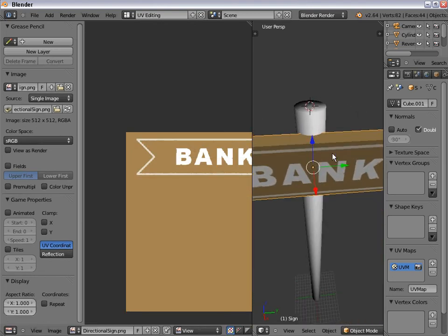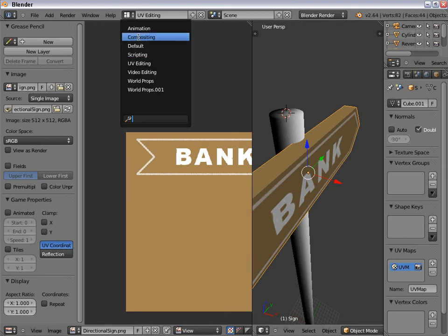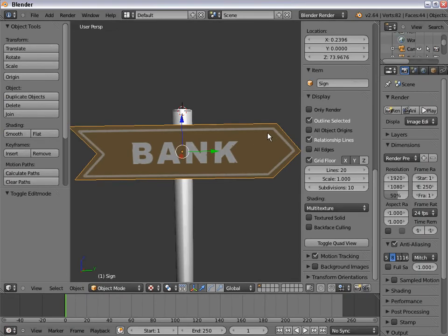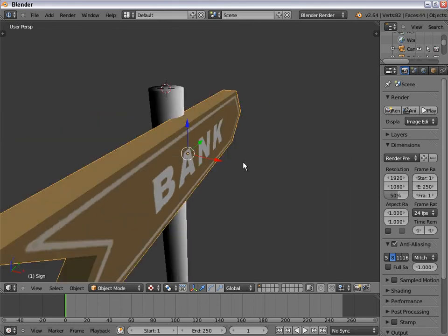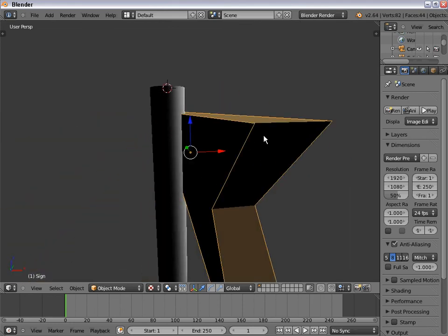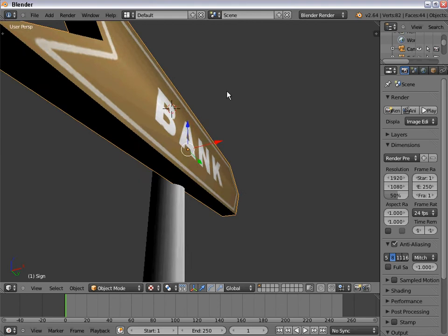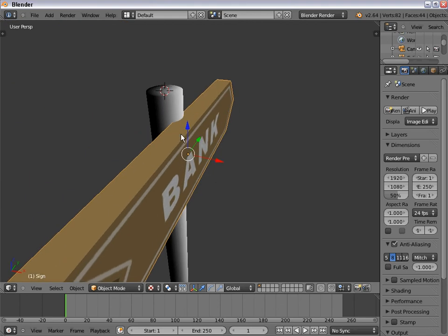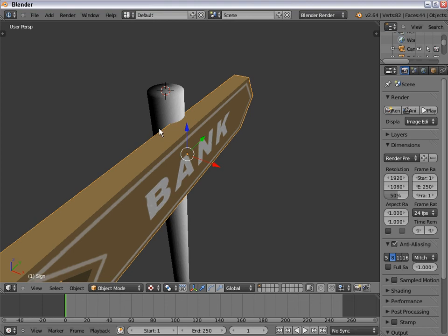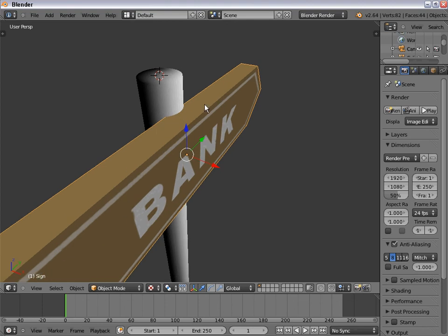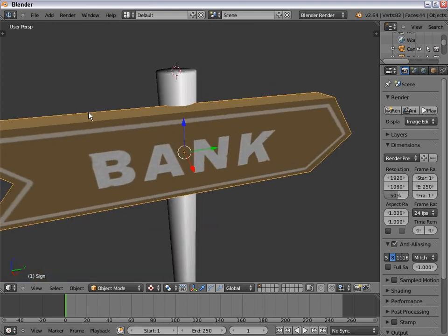The reverse of the sign, let's go into default mode and get rid of the tabs by pressing the T and the N key. The back of the edges of the sign are brown, but currently I have not created any UV coordinates for this part, so any texturing applied to the image will not be visible because all of the UVs of the vertices are 0 values.